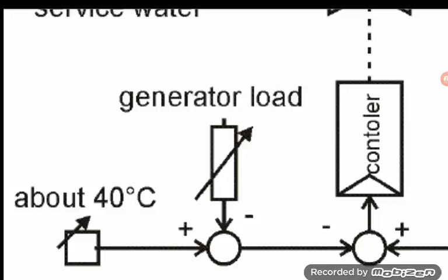So you increase the gas flow of your gas turbine, and therefore you increase the generator load. Maybe from 250 to 300 megawatts. Then the temperature of the hydrogen must go up because there's more current flowing on the stator. So you have more heat which comes from the stator into the hydrogen, so the hydrogen temperature goes up.